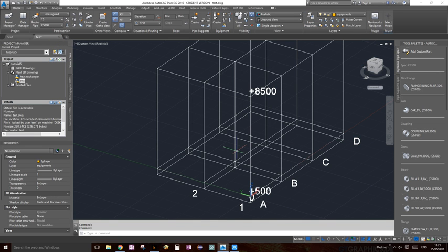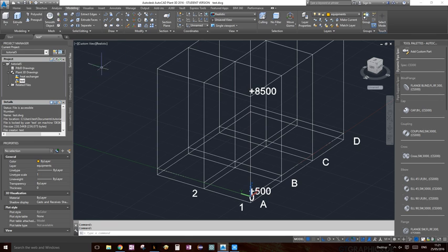So we're going to draw a line. I'm going to show you a different way of drawing a line because we're also going to be starting to work with the modeling ribbon. So go ahead and go to the modeling ribbon, and there you will see a palette called draw. Now there are a lot of options, some of which you can use a lot, and we will when the time comes. But usually the best way to learn is just hover over it.